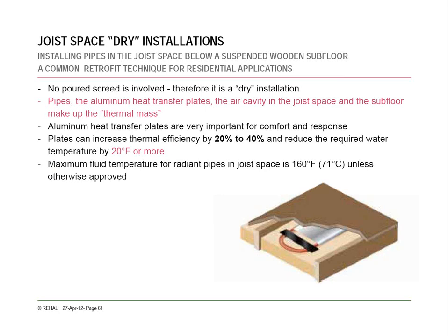Using plates does increase the thermal efficiency of these underfloor systems quite a bit, and you don't have to run quite as hot of water. Typically, your max temperature is 160, although usually, again, that's a lot lower. Ideally, it's a lot lower for more efficiency.